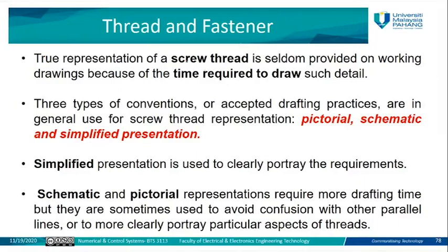The screw thread here actually is rarely or seldom shown in detail in the drawings. Why? Because it's very complicated. It's not easy to represent such a thread in the engineering drawing, but there are still some ways to represent it. There are three methods: pictorial, schematic, or simplified presentation.